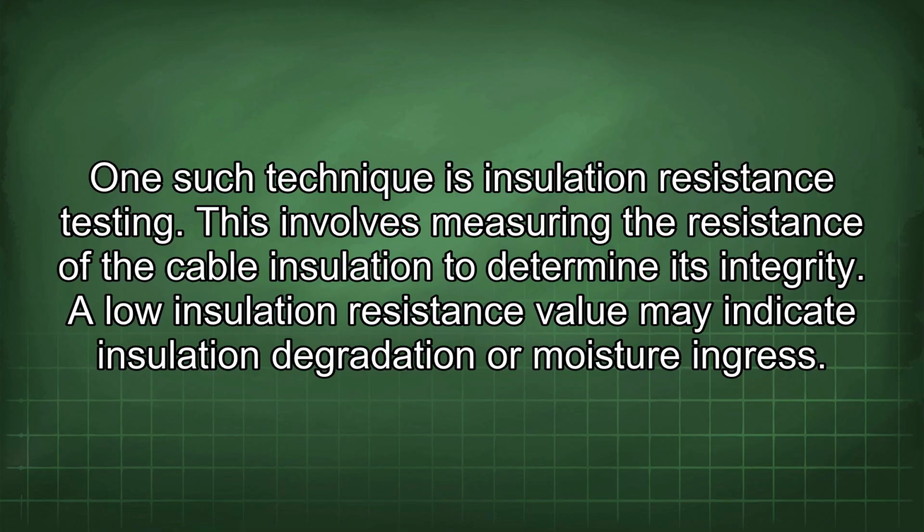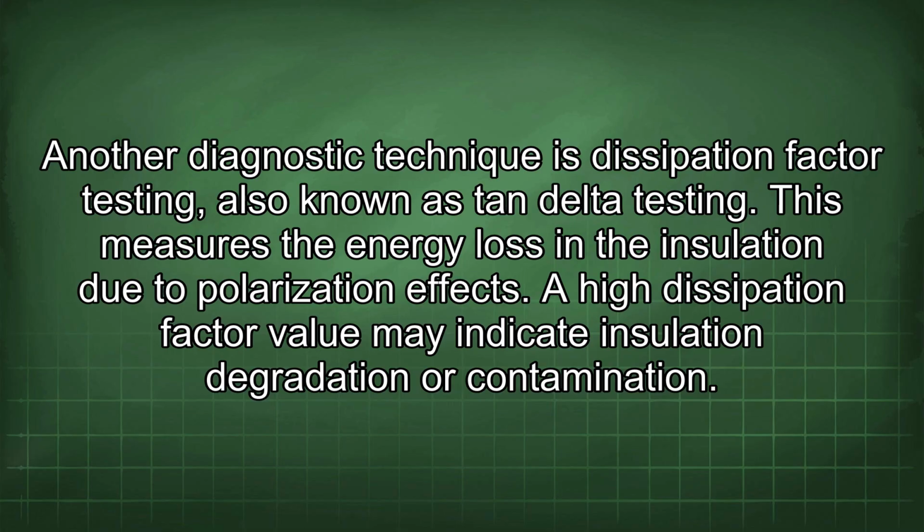This involves measuring the resistance of the cable insulation to determine its integrity. A low insulation resistance value may indicate insulation degradation or moisture ingress. Another diagnostic technique is dissipation factor testing, also known as tan delta testing.